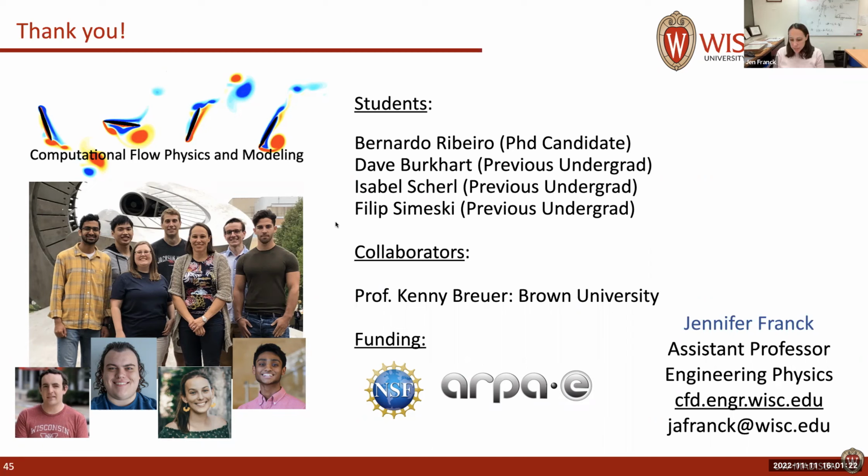And so far, we've stayed in the Reynolds number regime of about 50,000 and done careful comparisons against the flume results and the simulations. You don't see a big difference in terms of the LEVs convecting and the basic structure of the wake. They're very similar. So there might be three-dimensional perturbations changing the vortex dynamics, but they're not having a huge bulk effect on the wake or the trajectory of the vortex. So that was our conclusion from going from 2D to 3D.